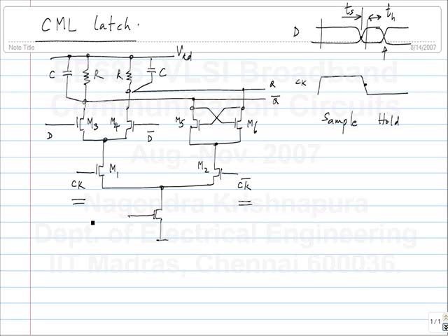Let's imagine that the clock, this M1, M2 switch instantaneously, okay? Just for sake of argument. Now what is the effect of M3, M4 or M5, M6? Why? Because it was opposite to all the answers that were given so far. Setup time is larger if M3, M4 is stronger or weaker? Yeah, in a way that is right.